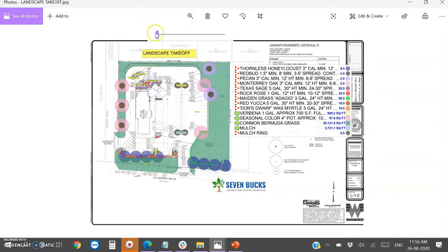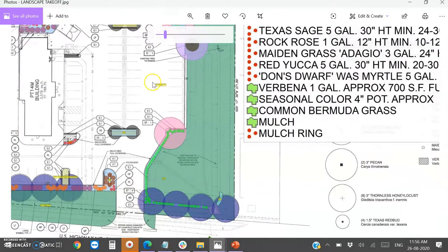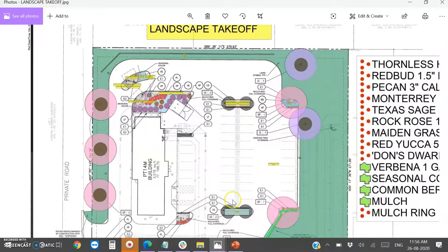Let me zoom in on a particular area. So this is very clear for you. This is small plants like shrubs or ground covers, and we can use drip line in this zone. Here we have trees, for which we need to use bubblers, and in the turf areas we can use either spray or rotor.